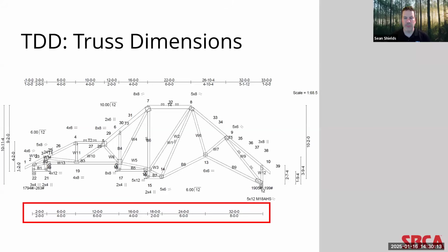Now, while the first and second numbers are pretty straightforward, typically you will see the third number listed in multiples of 4. Again, not always, but is listed in 4s. A 4 means then 1/4 of an inch, 4/16. 8 means a 1/2 inch. 12 means 3/4 of an inch. Now, that isn't to say that you won't see odd numbers. You'll see them quite often. And then those will just be read as 1/16. Again, the reason for this approach is to allow for quick calculations without requiring the use of decimal points or complicated fractions.